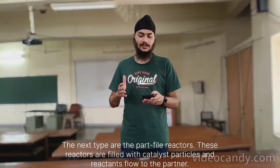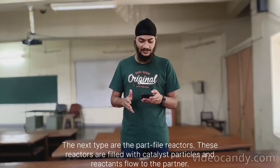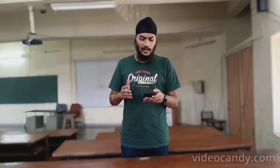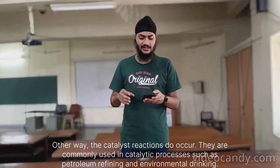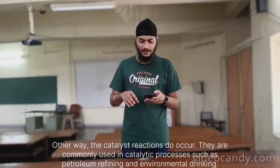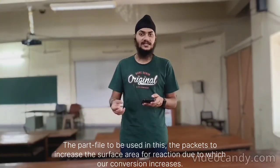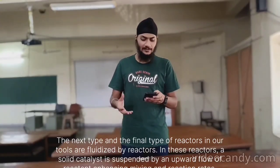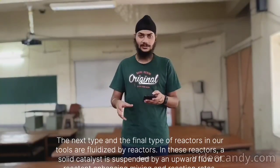The next type is the packed-bed reactor. These reactors are filled with catalyst particles and reactants flow through the pipe, allowing the catalytic reactions to occur. They are commonly used in catalytic processes such as petroleum refining and environmental treatment. The packing used in this increases the surface area for reaction, due to which our conversion increases. The next and final type of reactor in our case is the fluidized bed reactor.